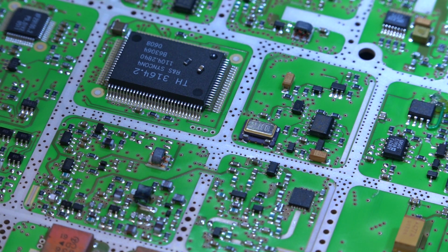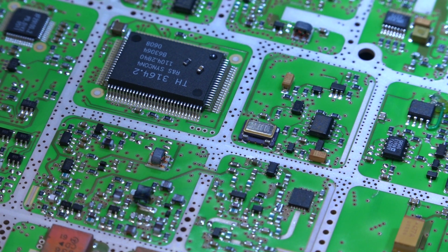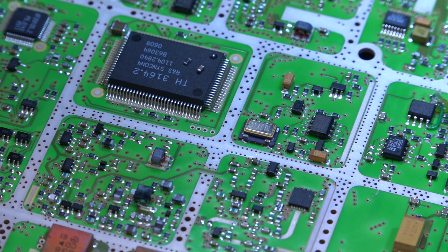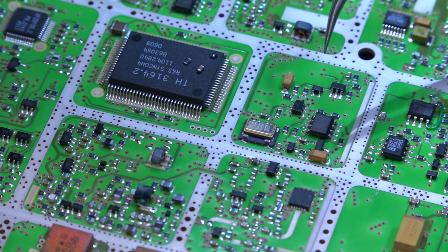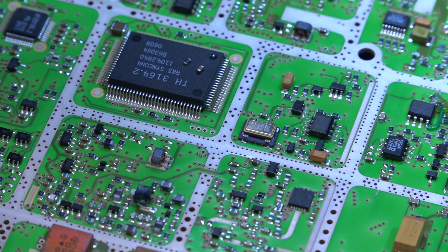When I took the capacitor out, it wasn't measuring any resistance anymore, and it's probably because I heated it up a lot and whatever flaw was in it might have cleared. It wasn't measuring a good capacitance to begin with. So I think that's probably the cause of failure, considering that this frequency divider, I think it's still okay. I haven't powered this on yet, so let's go ahead and put it back inside of the instrument and see if it does anything at all.